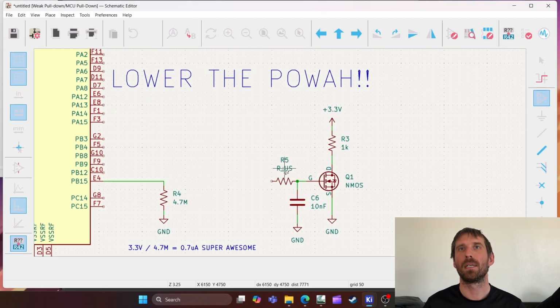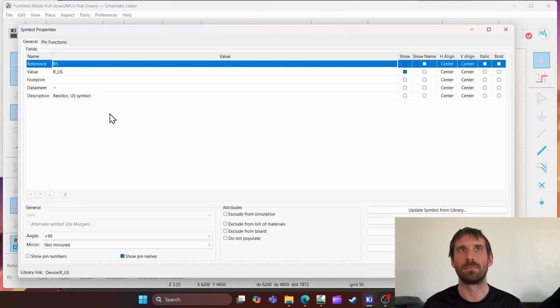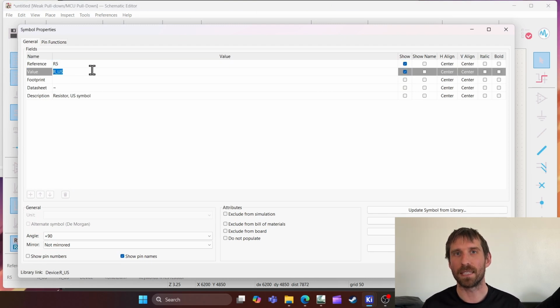See, I'm a little used to Altium and how it does things. KiCad, it's free. What are we going to put this as? Well, this serves a few purposes. One, it's going to form a low-pass filter. Two, I like gate resistors no matter what, to limit the current going into the MOSFET, just to ensure that we're not going over any kind of maximum limit, because I want my design to last forever. So we can go something like 200.